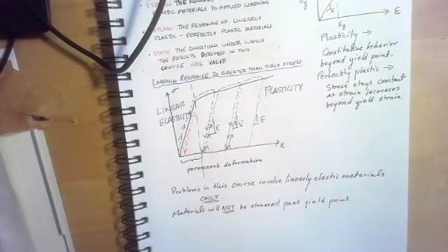And in the manufacture of many civil engineering products like reinforced concrete pipe, it's a common practice to take the reinforcing wire that is going to form the cage around which the concrete is placed. And you would start with wire that is about 10 KSI yield strength, and you would go through a drawing process where you would strain the material to very high strains.